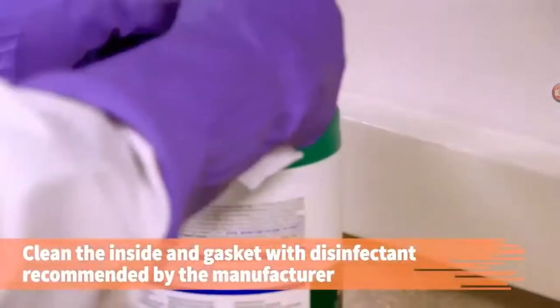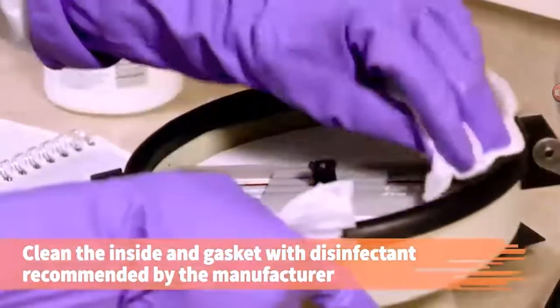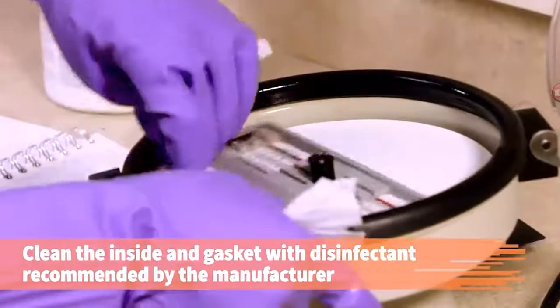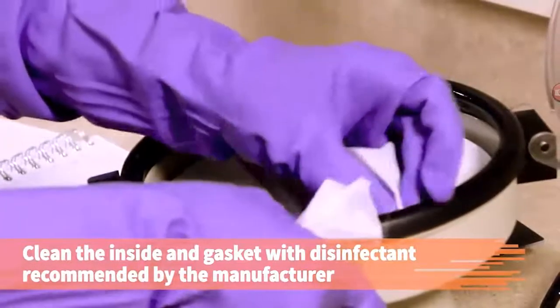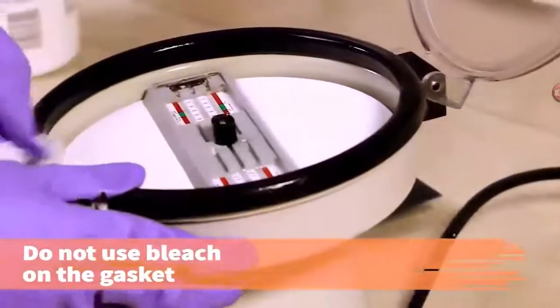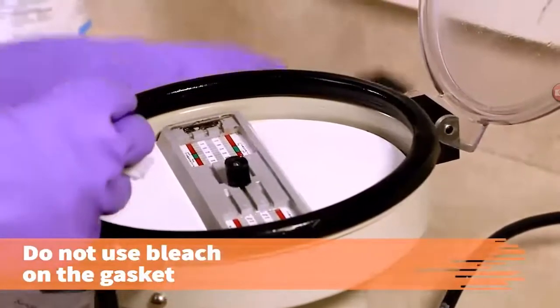As part of daily maintenance, clean the inside of the centrifuge and the gasket with a disinfectant recommended by the manufacturer. Plastic and non-metal parts may be cleaned with a fresh solution of 5% sodium hypochlorite or bleach mixed 1 to 10 with water. 1 part bleach plus 9 parts water. Do not use bleach on the gasket because it may harden the rubber.